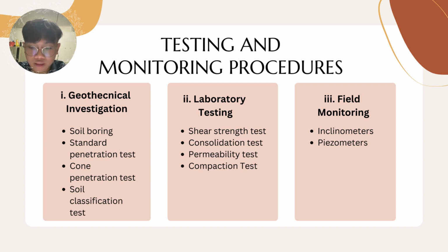And last but not least is field monitoring, which includes inclinometers, which can assess the retaining structure through displacement or motion, and piezometers, which can determine the pore water pressure present in the soil. So field monitoring is a step to assess and monitor the behavior of the earth retaining structure and the surrounding soil, where it entails the installation of sensors. So now I'll pass the presentation to the next person.